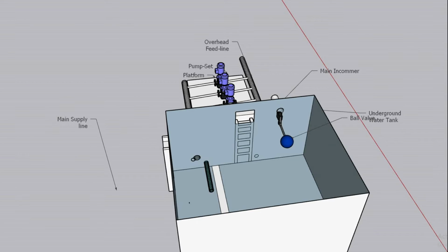Not only that, but also we need to clean all this part, which is actually not required, which will take a lot of time. And most importantly, when we're cleaning this, it consumes a lot of time, and in that time the building is not covered with any fire protection. So imagine if you completely remove the water, if God forbid any fire happened at that time, you're putting the building at risk. So here, as I said, for the UAE, it is forbidden to empty the water tank without informing the civil defense. So you have to inform the civil defense.